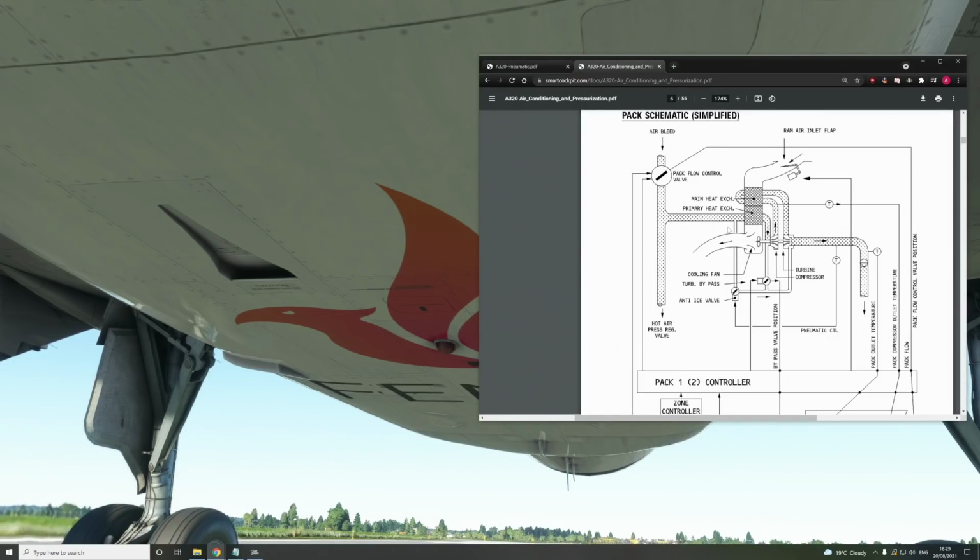So there's a little fan here, and it's not documented. But because it was a physical simulation, the air coming through here was just not cool enough. There wasn't enough air coming through, so we were getting a bunch of overheats and all sorts of crazy stuff. Until we realized there's a fan in there, and using the diameter of the fan that is pushing the air through this ducting, and how wide the ducting is, we could go, okay, the system now works as it should. It's just an example of the level of detail, the physical simulation, and the lengths we've gone to in order to create this.